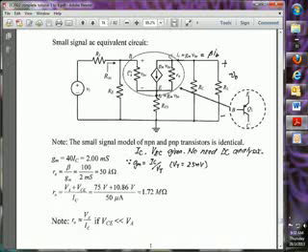So we can draw this in a simple form, where the voltage here is VB to ground, the current going into VB is IB, and this point is connected to RE to ground. For input resistance, you can ignore R0, we can open R0, so the current gmVBE, which is equal to beta IB, flows down.